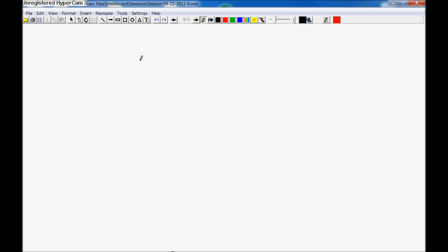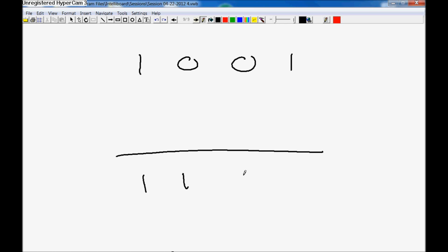If I had the same nibble of data and I wanted to add to it, so I want this as the output, I'd use OR because I'm adding to it. So I'd use a 1 to add to it and a 0 to preserve it, and there we go, it stays the same. Now that's just single step.